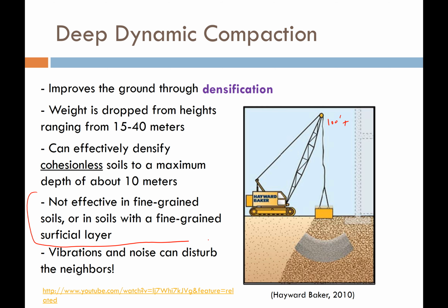This method is not effective in fine-grained soils, clays or silts, or soils that have a fine-grained superficial layer. So if I have a layer up here that is clay and then sand down below, that energy is just going to get all gummed up in the clay and won't make it down into the sand. So we want to avoid any time where we have a fine-grained layer near the ground surface.